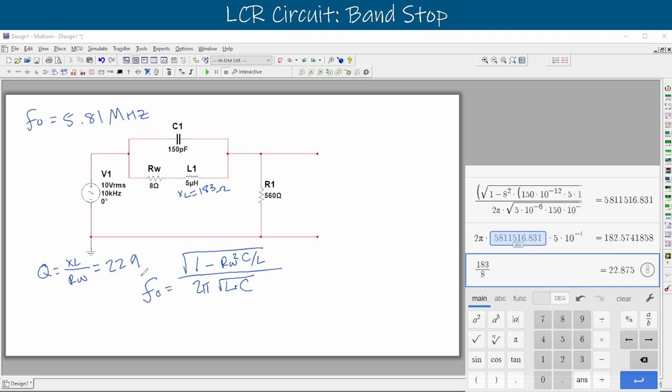And that's a factor. So that is going to be our quality for that one. And we can use that to determine our total Z value, our Z value from a purely resistive standpoint. And that's going to be ZR. That's going to be our linear Z value, and that includes the winding resistance as well as our Q factor there. So we'll set this equal to our winding resistance of 8 ohms multiplied by the Q squared plus 1. That's the equation for that.